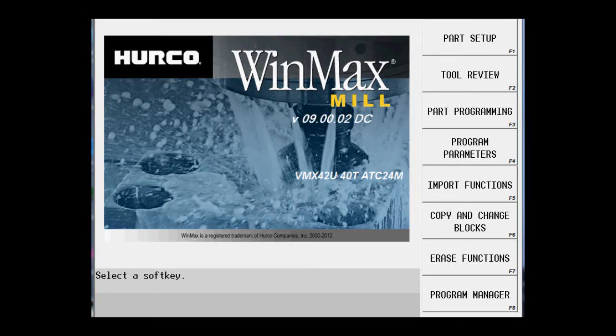In the print Intro-27 in your packet, we're going to learn how to use patterns. In this particular print, we have two parts that are identical, and each part has a grid pattern of 25 holes. So what we're going to do is create one hole, the bottom left hole of the left part, and then pattern that hole into the grid pattern, and then take that entire group of patterns and pattern it to the right 5 inches to create the second part.